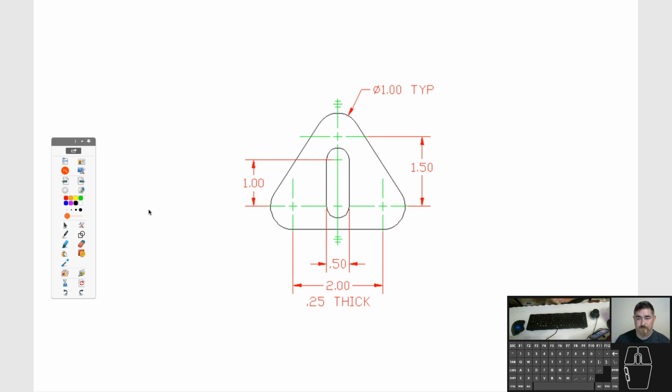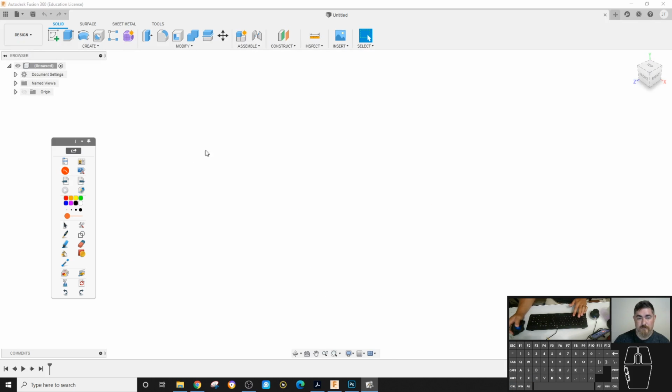So if you know where that point is, like if these lines extended up and it told me the point would be here, and here, and here, I would draw it with sharp corners and then add fillets later. But this one is telling me where my center points are, and the radius of those arcs is making up the size. So I kind of have to use those in the sketch. So let's do that.